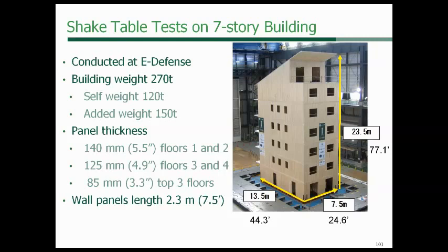There was some cracking at the connections at the bottom, which is to be expected after a large seismic event like that. But overall, I think everyone who has seen this test and witnessed the test is fairly impressed with the resistance to seismic loads that CLT is displaying, and we think it's going to be a good solution for seismic resistant structures in the future.